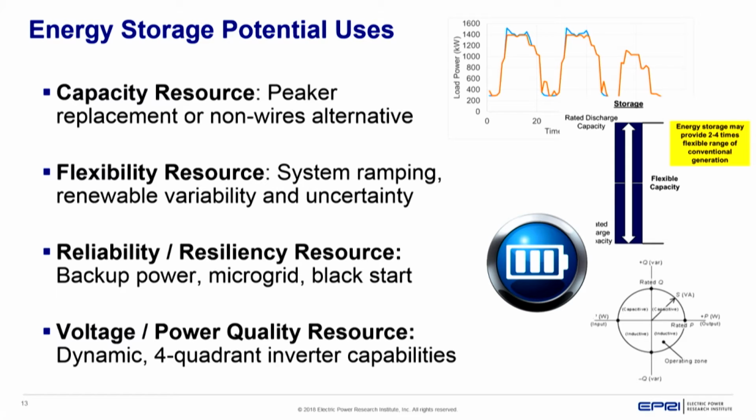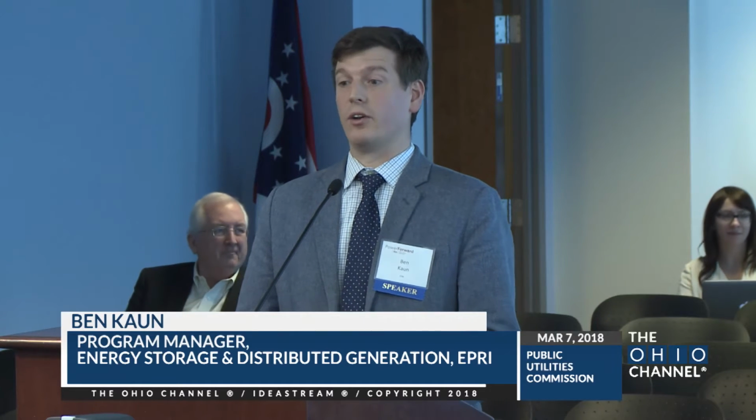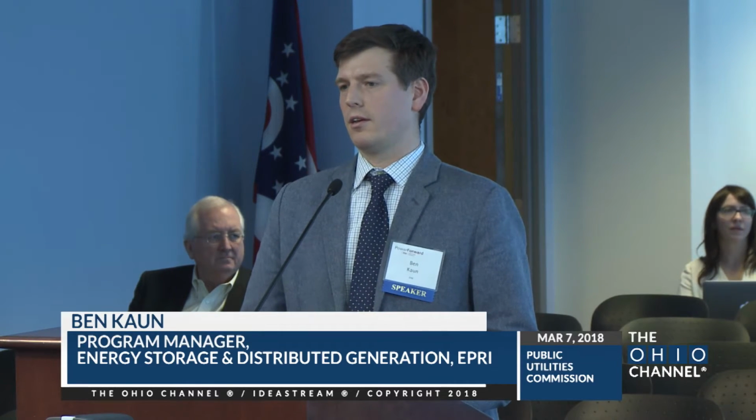And then finally, energy storage has advanced power electronics on board, so it can do dynamic 4-quadrant operation and deal with things like voltage variations quite readily, without even necessarily needing to tap into the reservoir of energy that it has on board. But these capabilities come with the energy storage product.